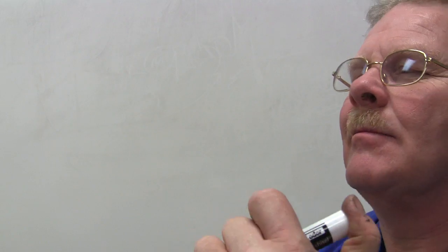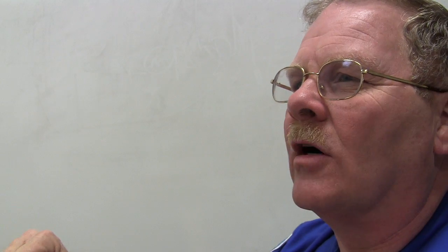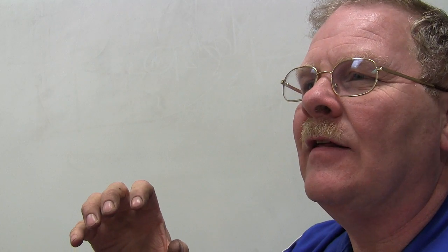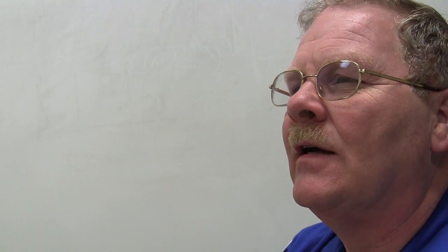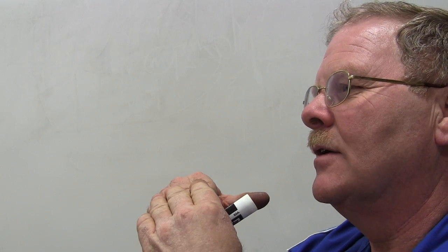Now here's something else. If you ever see a boot between a mass airflow sensor and the intake that has a little crack in it, sometimes you can't see them because that's a convoluted boot. Somebody gives it the gas and the engine torques, and it opens up that crack. Then the engine will try to stall down some, and it closes the crack back up. And then it tries to open back up. Then you've got a lot of unmetered air, and it goes back and forth. I saw one with a mass airflow sensor partially unplugged, and it would torque, and it would plug and unplug it and do that. I kept expecting to find a crack in that boot.